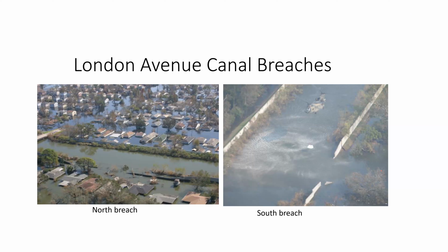Okay, now the question is, what happens in a piping failure? Soil gets washed away from underneath the foundation. So it gets washed away underneath the foundation, right? How does it get washed away? What is the mechanism? Seepage water uplifts the soil.